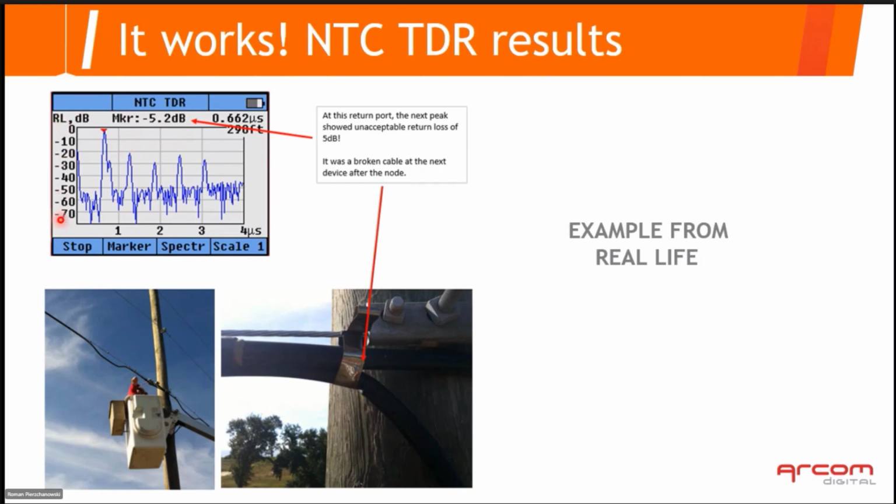You can see negative numbers on the scale, because return loss by math is really a negative number. Equipment vendors are showing positive, just for simple understanding that the higher number, the better return loss is. So we decided also to switch our scale to positive numbers.